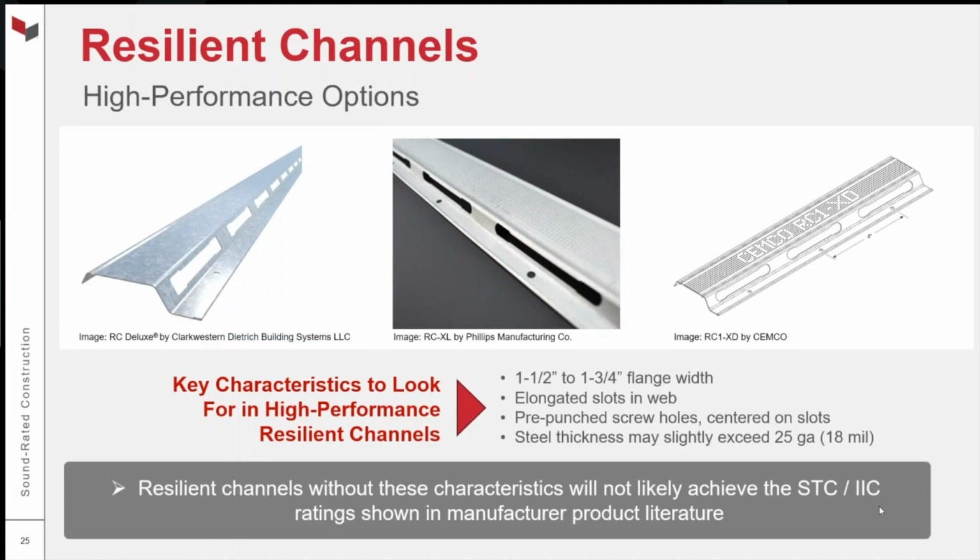invariably, for the STC and IIC ratings that you see in published literature, you should assume that they're using one of these channels. They're using a high performance resilient channel. If you use a channel that doesn't look like this, that doesn't have these characteristics, you should be expecting that your IIC and STC values are going to be lower than what you see in published literature from manufacturers or different design guides.